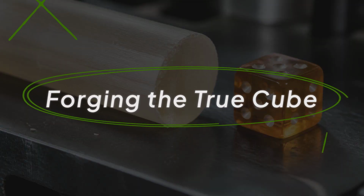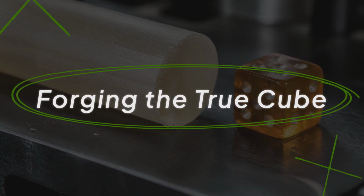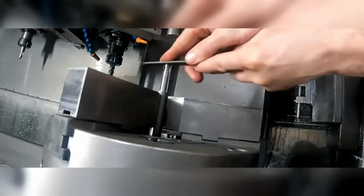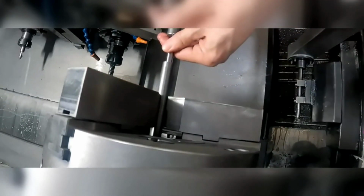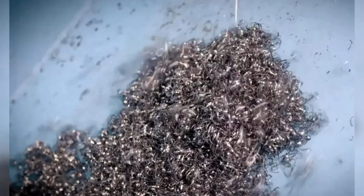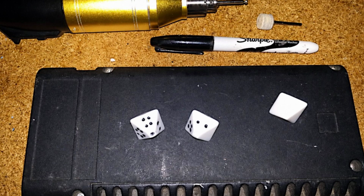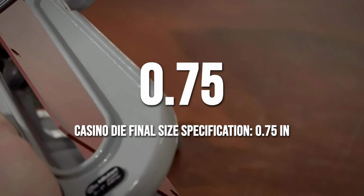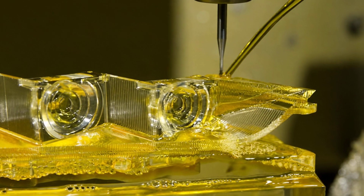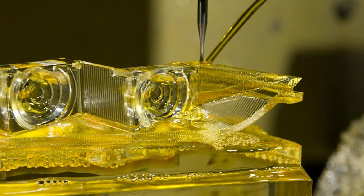The physical transformation of a raw extruded rod of cellulose acetate into a finished gaming instrument begins on the machine shop floor. Here, a machinist mounts the solid polymer bar into a precision cutter, slicing the stock into rough, oversized blanks. These initial pieces are only approximations of a cube, measuring slightly larger than the final 3/4 of an inch specification. Next, the blanks are loaded into a CNC mill.